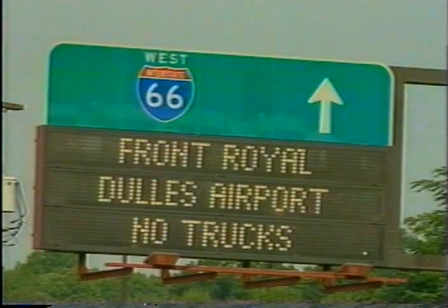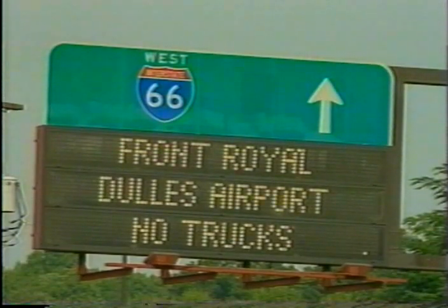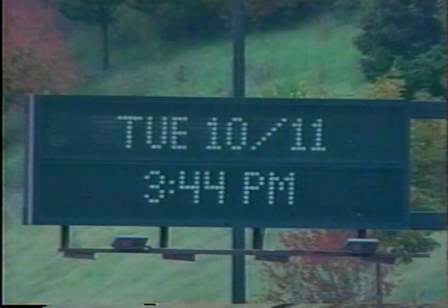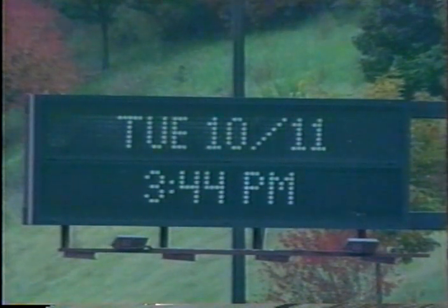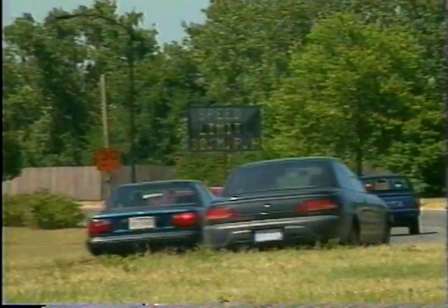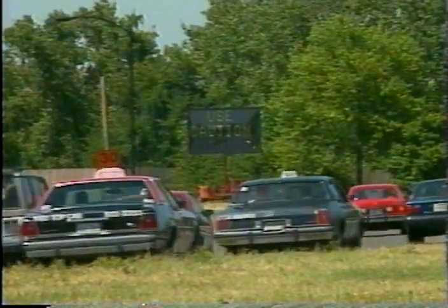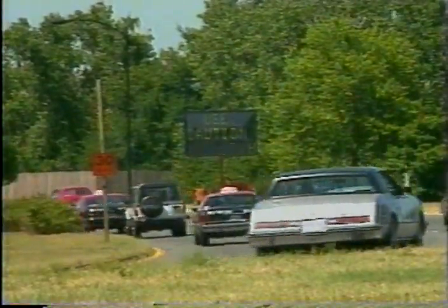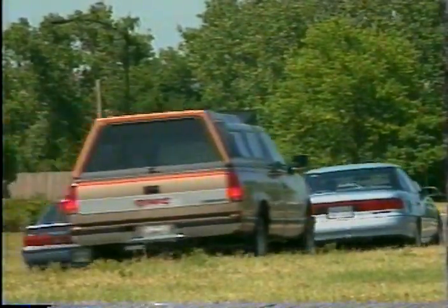Permanent installations are used for areas where predictable conditions will require a message. These signs can be changed remotely, on-site, or automatically at a fixed time of day. Transportable signs are used more for construction or incident areas. They can have a changeable message or a fixed one.